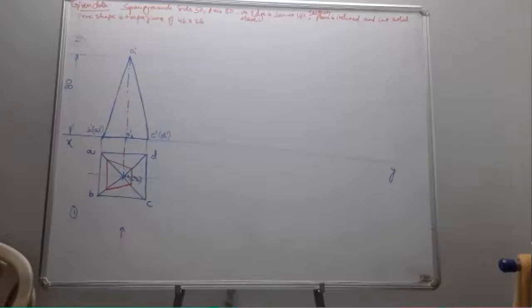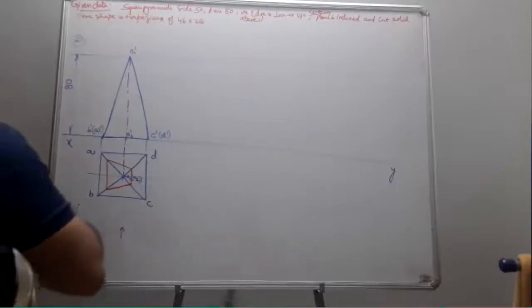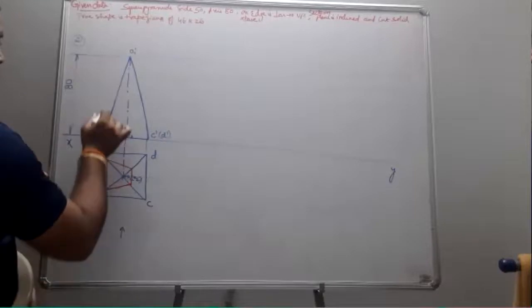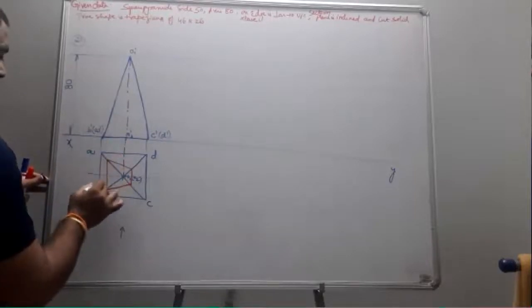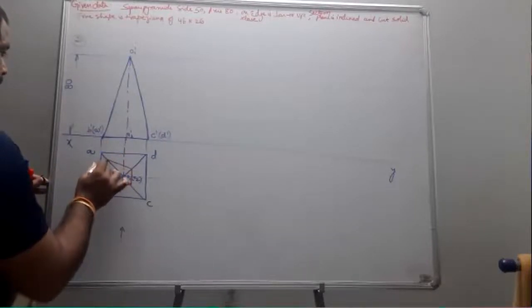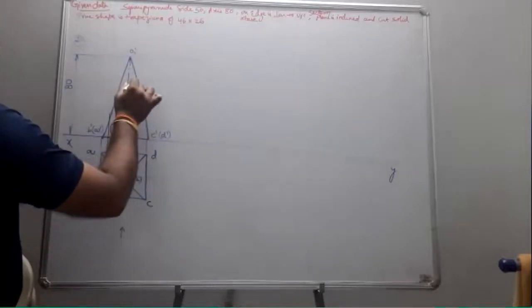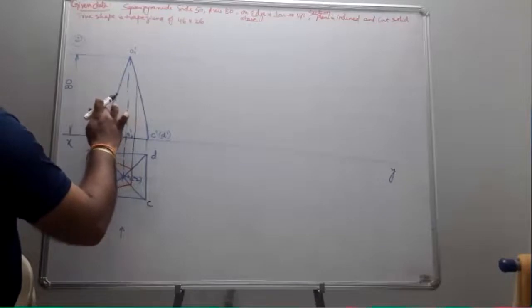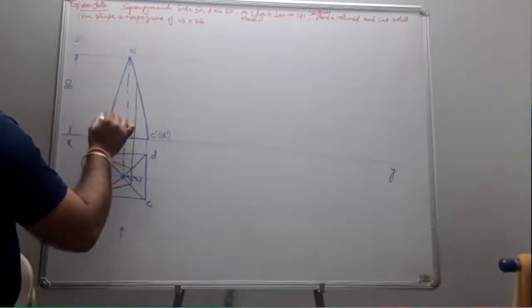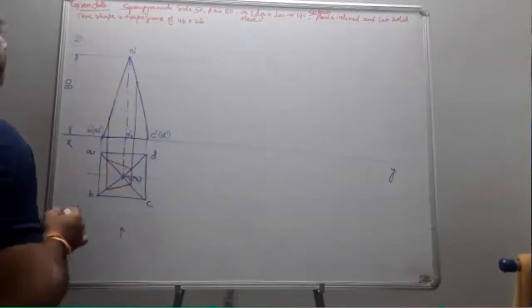Now, in this regard, I just mark my numbers. First of all, you are going to project this obtained sectional view to the top. That is for the front. I just project these lines. This was the line of projector, and these two are going to cut your cone solid at these particular points.